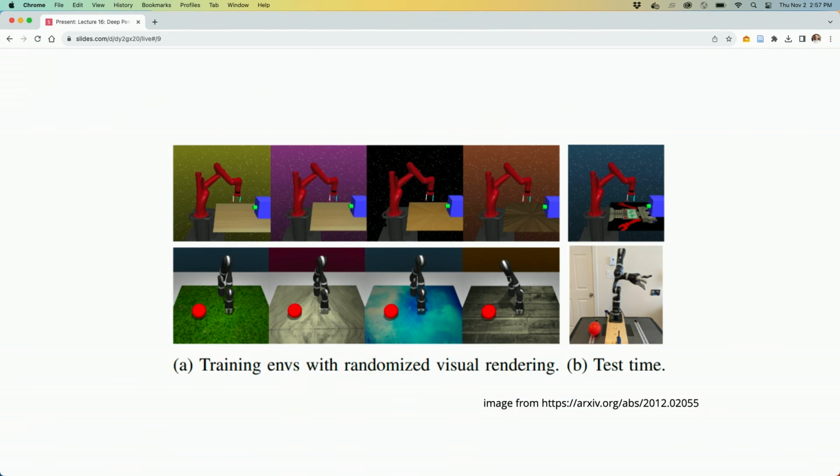Domain randomization is the generic term for it, okay? You can imagine rendering my scenes not only with the original simulation assets, but starting to throw down all sorts of different textures, all sorts of different lighting conditions, all sorts of distractors. This example doesn't actually have distractors. When we were doing the silverware project, you'd see a bin full of silverware, and then you'd see an elephant in the middle of it, because you knew the real system was going to have occlusions.